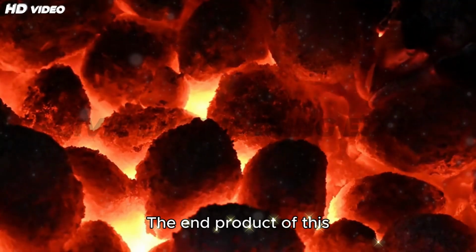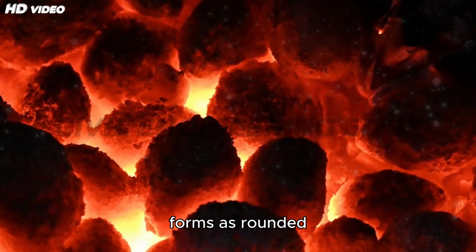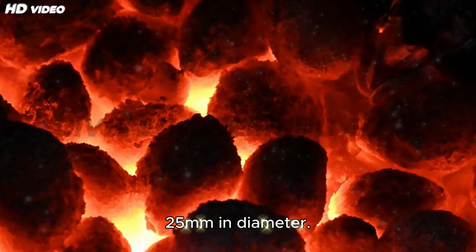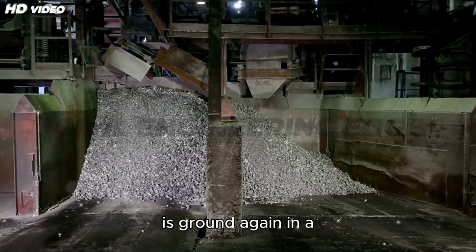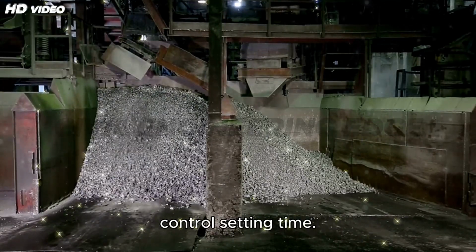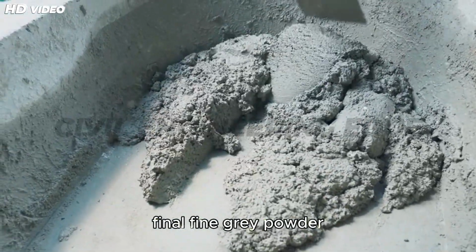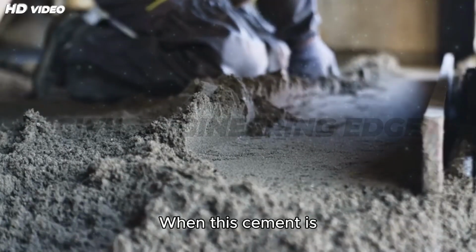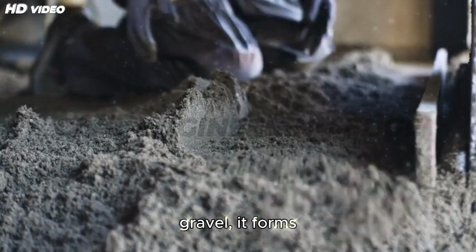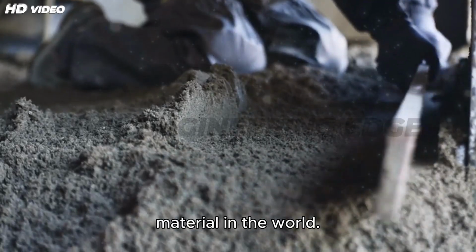The end product of this thermal process is known as clinker, which forms as rounded nodules between 1 millimeter to 25 millimeters in diameter. Once cooled, the clinker is ground again in a cement mill, where it's combined with gypsum to control setting time. This produces the final fine gray powder we know as cement. When this cement is mixed with water and aggregates like sand and gravel, it forms concrete, the most widely used construction material in the world.